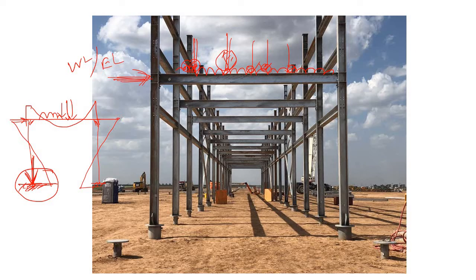So first, to design this pile, what do you need to consider? First one is you need to consider the compressive load. Second, you can see here that you will have some bending moment. So this is the bending moment diagram. In this zone you will have a bending moment acting like this. So this is the bending moment diagram acting on this particular column. At this level you will have some bending moment, so you need to design this particular pile to counter this bending moment.